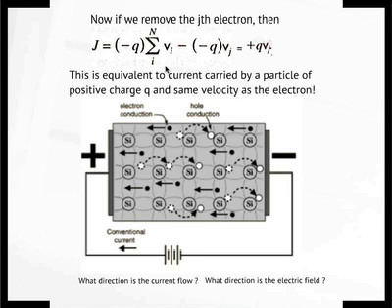Okay. So we have to add that into the equation. So you have to add an extra term into that sum, which means that now you have a term which looks like that. So now your current is given by plus Q times velocity. So it's the opposite charge of an electron. Of course, if you think about it, it makes common sense. An absence of an electron should behave like a positively charged particle. Right? The electron's gone. Okay, that's what's called a hole.